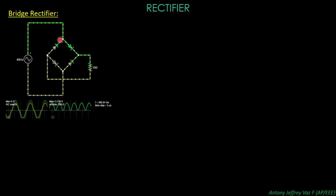So the electrons start to flow through this diode and enter the resistance. After the resistance, it again comes back through this position and is present here. This diode is in reverse bias, and this diode is also in reverse bias, so the current starts to flow through this D2 diode and returns back to the supply.